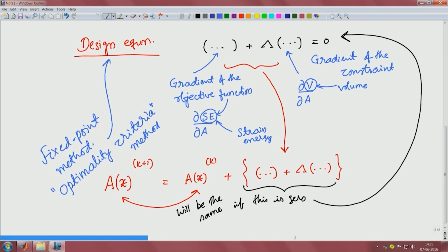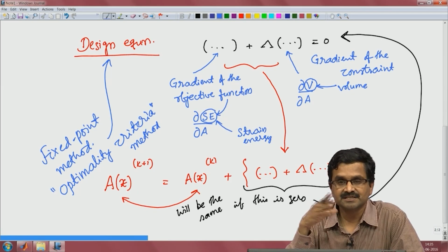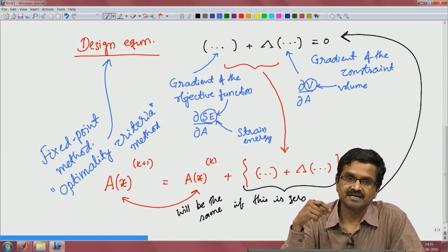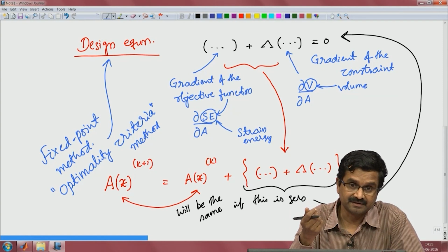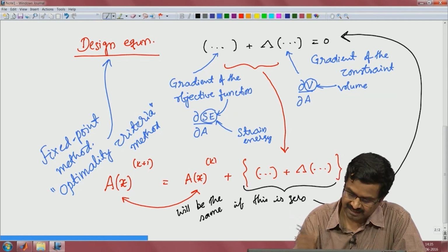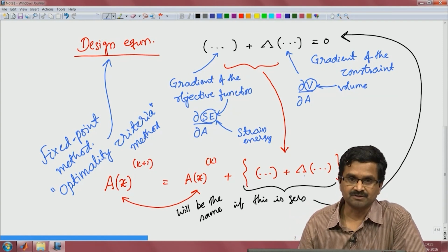This is the optimality criterion design equation, which we interpreted last time for this stiffest structure problem for given volume as something that says strain is constant. Since we are assuming linear elastic material, stress is also constant, and hence strain energy density is also constant. Okay. That is the optimality criterion, and we are using that to update iteratively and solve for the problem.